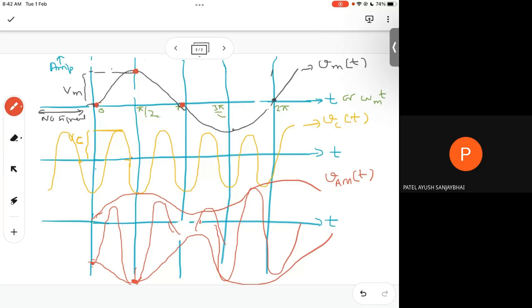That means my amplitude of the carrier wave is varied. This is the envelope. Basically, this is not the waveform, but this is the envelope, which we say. So frequency remains the same as the carrier. If you see, there was no signal here, but the carrier was there. So my AM wave also will have no signal here. But here, frequency remains the same as the carrier frequency.